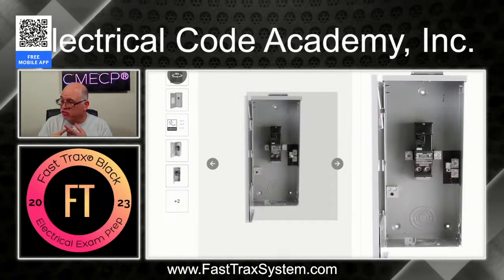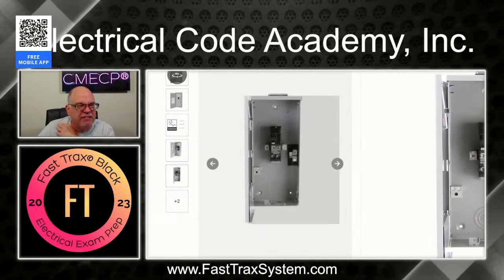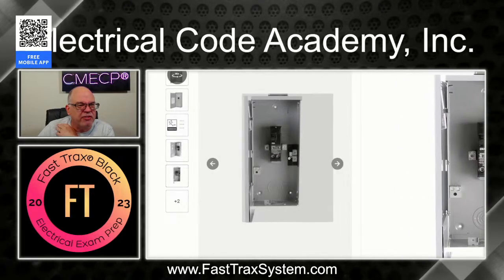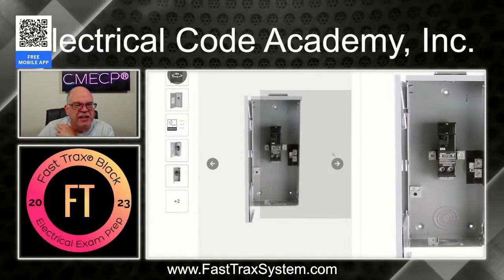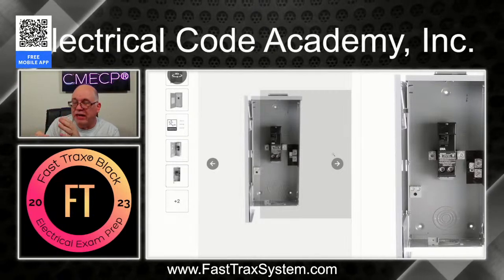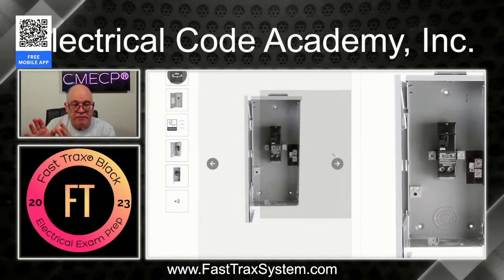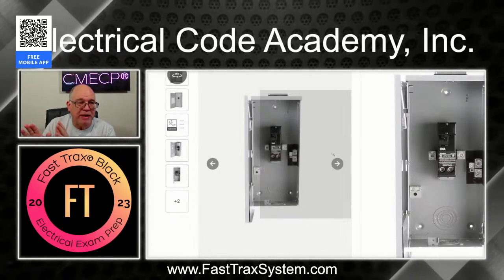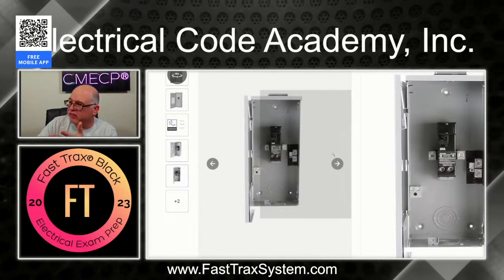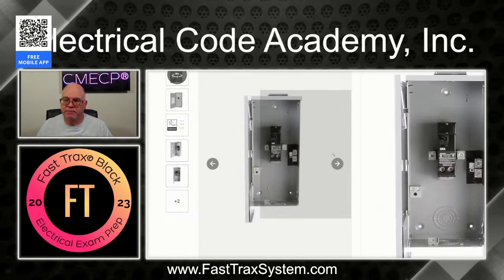Now, this is the service disconnect. If you look over here on the right, right here where my mouse is, although I'll try to move it a little bit to the right. See there, it's got that hole. So that is where you're going to put your main bonding jumper. And this is the service. It's suitable for use as service. And this is going to be my service equipment. It's going to be my service disconnect, my emergency disconnect, and then it's going to create a feeder on the load side of it. Okay.